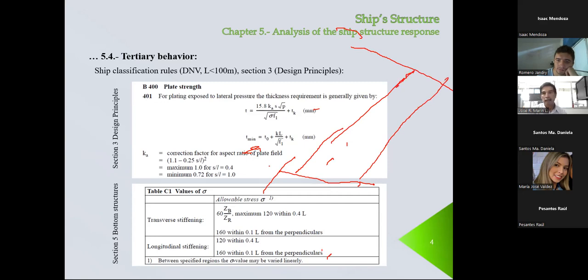System, okay? The transverse elements are closer than the longitudinal elements. In that case, remember that the largest bending moment is aligned in the direction of the shortest side. So in this case, the bending moment in this direction is larger than the bending moment in this direction. So if this is X, this bending moment will generate a sigma X, very important.